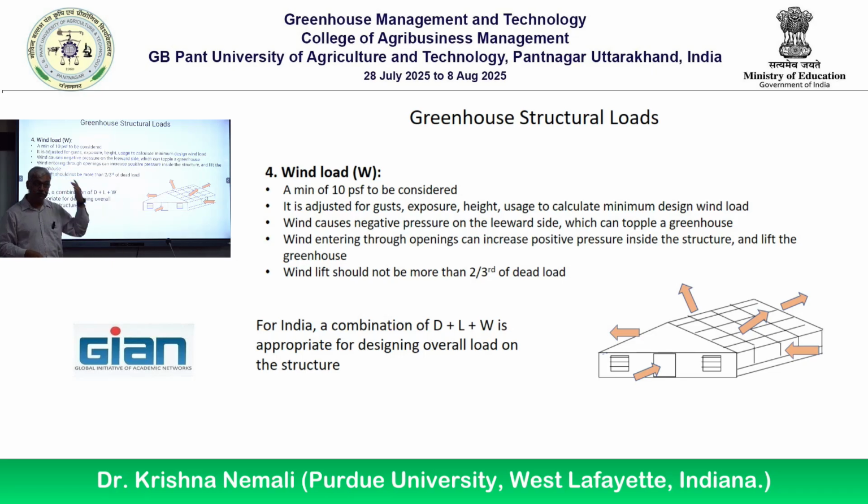Otherwise, your structure is blown away, permanently blown away. The live load happens when people are up there or you're hanging plants. Snow load happens when there is snow on top of the plants. But the dead load is important because the wind is hitting that, and the wind speed should not be able to take the structure off, and that is a requirement.